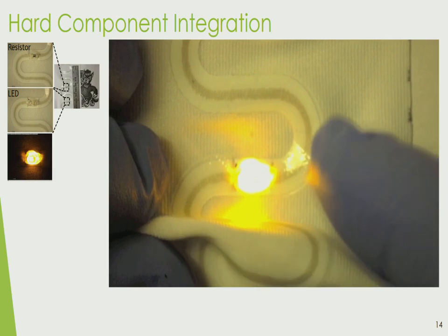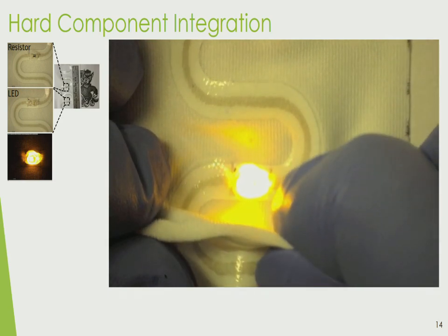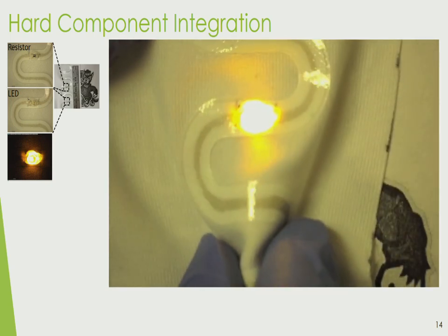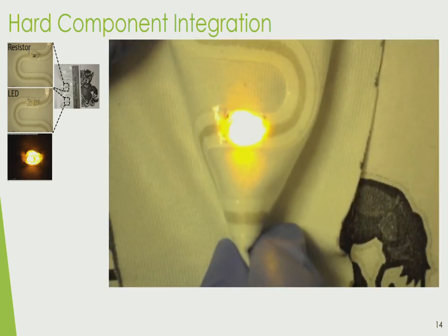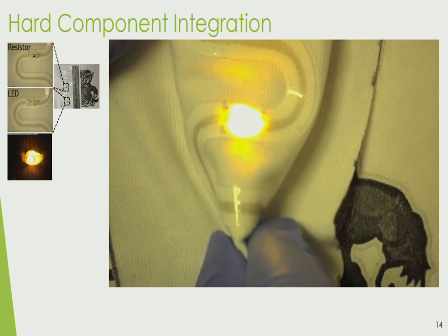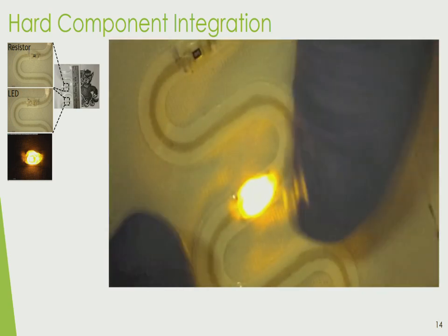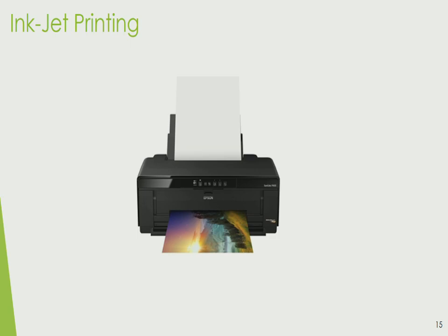But you can see that these films basically guard the textile from the body, or they guard the electronics from the body, right? So you can't breathe. That material is not breathable. So we need to introduce materials that are breathable, so that we retain some of the properties of the textile that we so desire. That's where we start looking at inkjet printing.